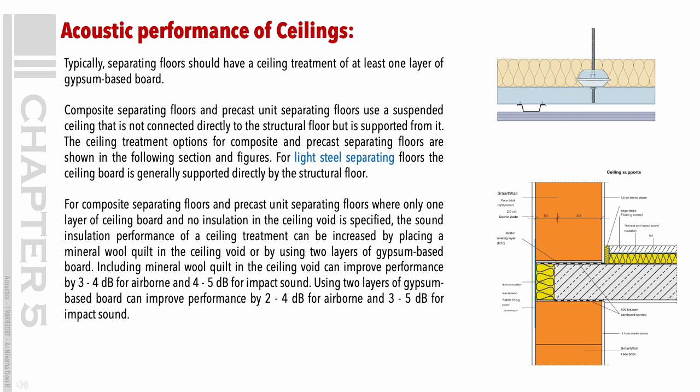Composite separating floors and precast unit separating floors use a suspended ceiling that is not connected directly to the structural floor but is supported from it. The ceiling treatment options for composite and precast separating floors are shown in the following section and figures. For light steel separating floors, the ceiling board is generally supported directly by the structural floor.